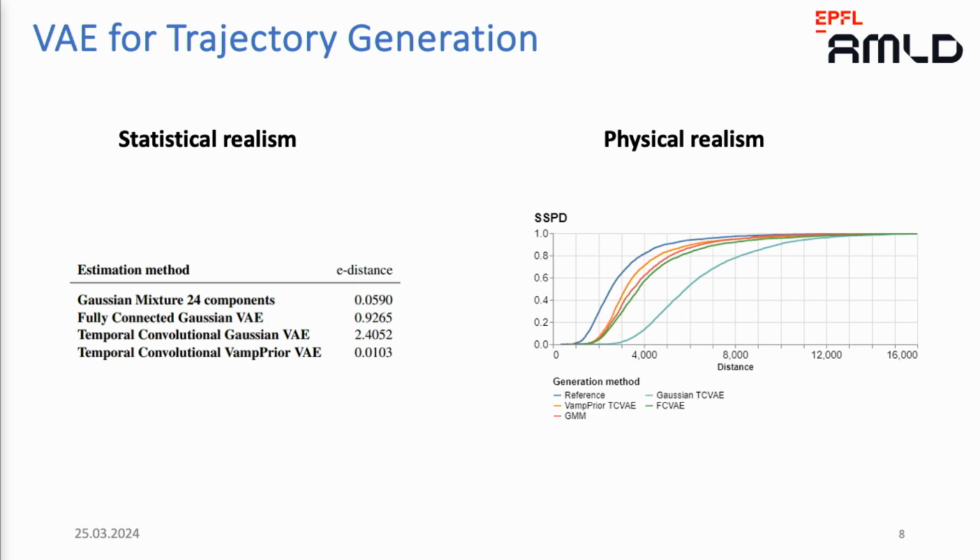It is based on flight dynamics equations and gives as output a trajectory that goes through those waypoints. The very simple idea I had is that if I take a synthetic trajectory and give it to my aircraft performance model, the output of this model should be very close to the synthetic trajectory I have given as input. So this is what I'm measuring here.